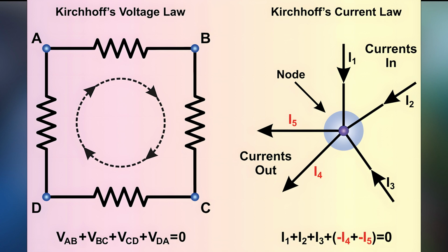Any closed loop in a circuit, the voltages must sum to 0, because again, if that was not the case, you'd be violating conservation of energy. So those two laws are the basic conceptual underpinning that is necessary for basic circuit analysis. Although we won't actually do circuit analysis because it can get a bit tricky, if you understand those points, then you understand a fair bit about the behavior of electricity, because they come directly out of the fundamental physics. It's just conservation of charge and conservation of energy that is really all that's underpinning Kirchhoff's laws.